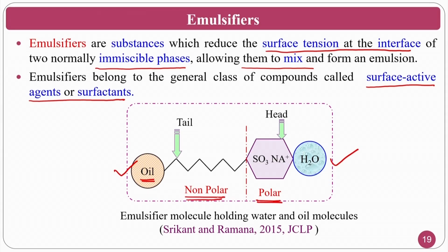The polar head will go and attach to the H2O molecule, that is a water molecule, and the non-polar tail will go and attach to the oil molecule. In that circumstance, I have two things, one is water, another one is oil. The polar head will come and hold the water and the non-polar tail the oil, so that it will mix properly. That is how the mechanism of the emulsifier works between the two immiscible fluids of the cutting fluid.